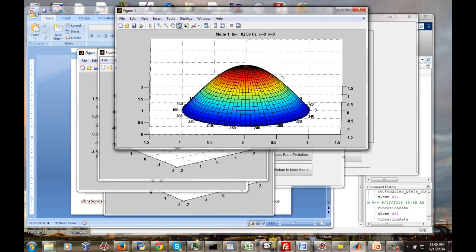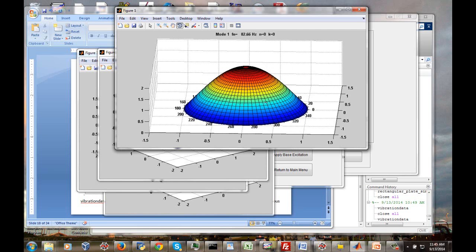Of course, there are some higher mode things going on too that come into play, kind of as higher order term effects. It's also going to turn out for this plate, where we have uniform base excitation, that all of the modes that can be excited, another way to say that is all of the modes that have non-zero participation factors, are axisymmetric. So we don't need to consider what the angle is when we look at the stresses and the response amplitudes, because it's sweeping around 360 degrees, it's all the same for a given radius.